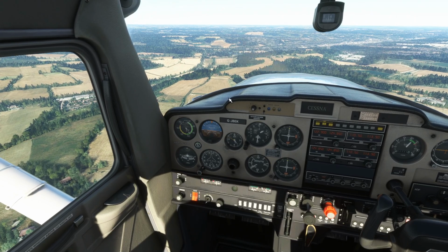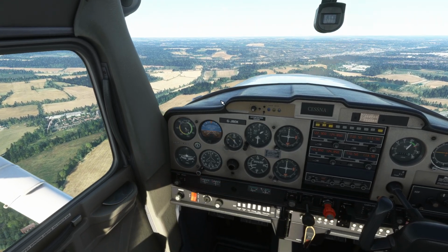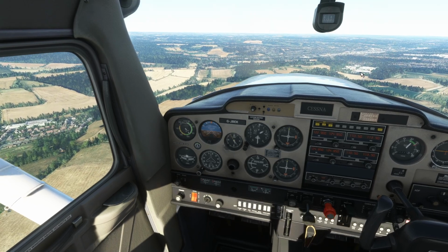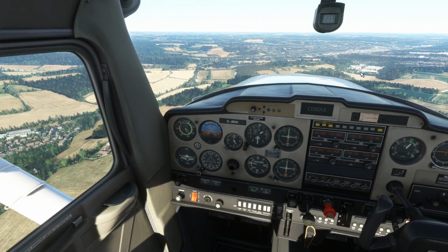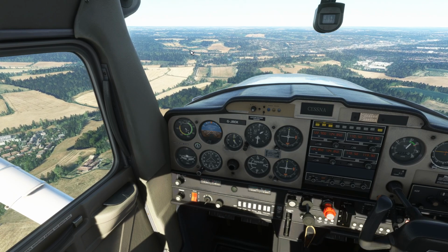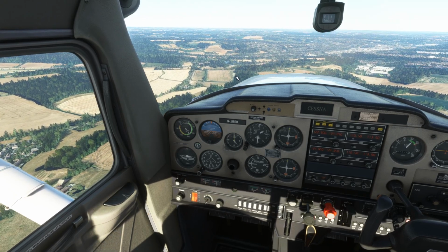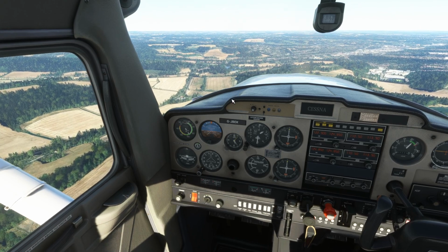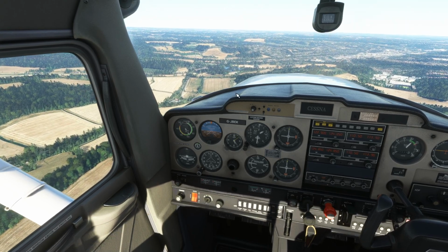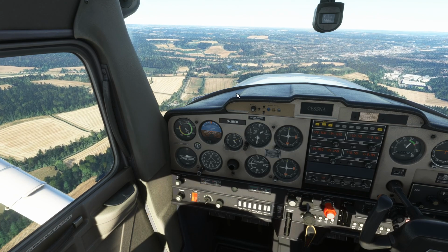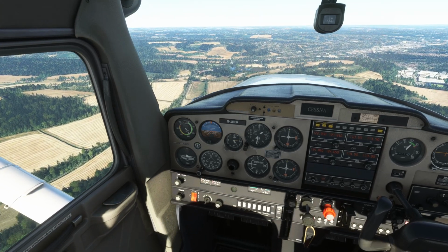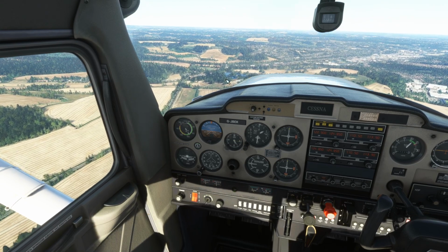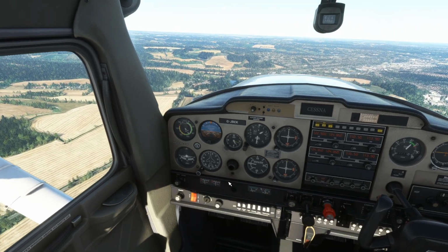Okay, so we are looking to turn just inside this road and the edge of the industrial estate towards 150 degrees, which will be directly into the wind. We're looking for the house that will be below us. We're also looking to cross this water, or to approach the water at least. We're just to the right of it. So you can see the aircraft's pointing this direction, but we're travelling in this direction, so we're crabbing across the wind.